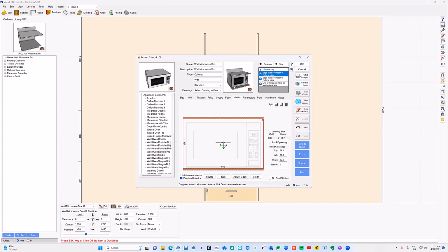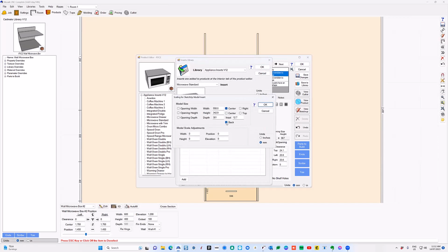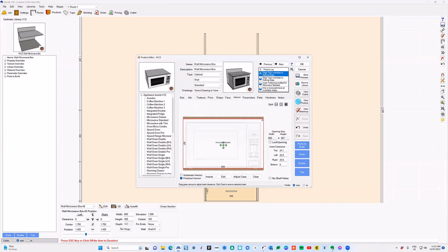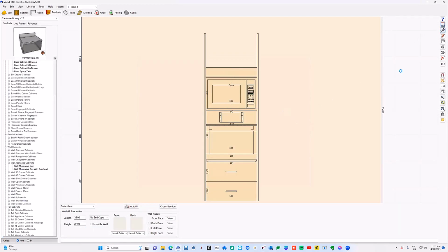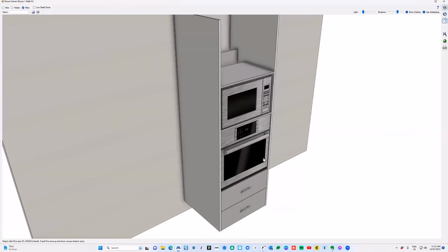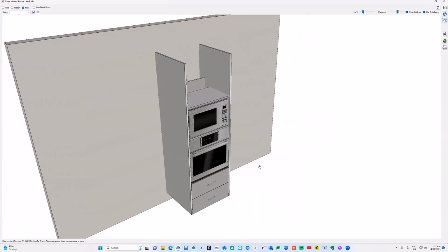Again, you can muck around with the positioning of it. You can go to edit and then scale. And in the depth here, I can change my depth. I could position it where I want. I might want to go 10 mil back from the front of the opening. You've got various control there in changing that, but it's helping you build a product that's going to be consistent with the way you want to manufacture things.